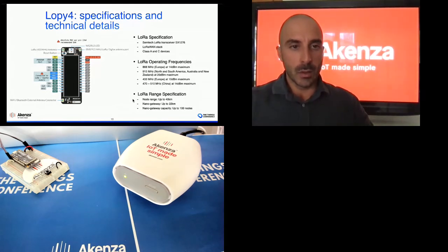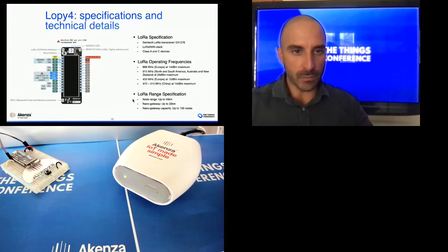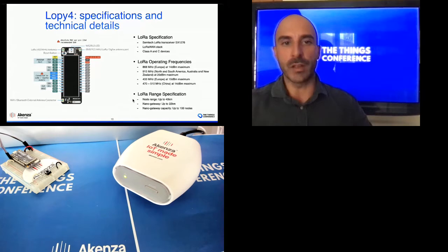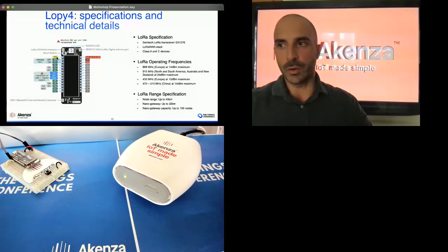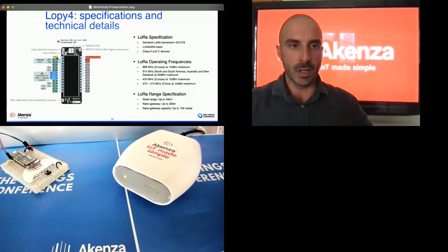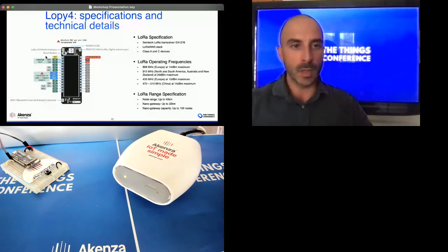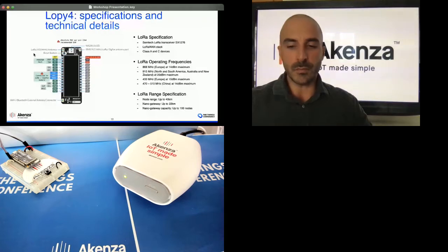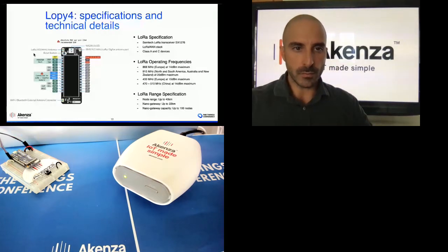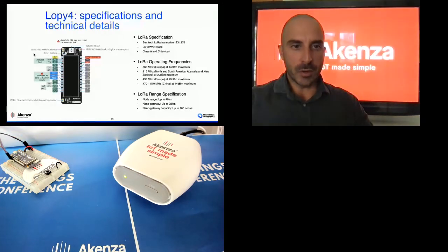And well, what we have used, you can already see there. We have voltage in. We have chosen the 5.5 as it's more stable in our opinion. The ground here. Then we have the reset button that we will use for uploading the firmware. It is for the upload mode for the LoPy. And then we have the two program pins, the RX and TX, which are used for the upload of the firmware on the chipset. So let's see the project setup on the software side.